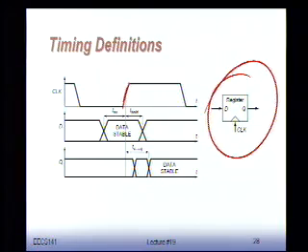Actually, it turns out that for a register to work, it is a good idea to keep the data stable, and actually it's a necessity, that your data doesn't change. So you have your data changing back and forth, and then you're going to sample it here at the rising edge of this clock. It is essential that we keep the data stable a little bit before that edge event.